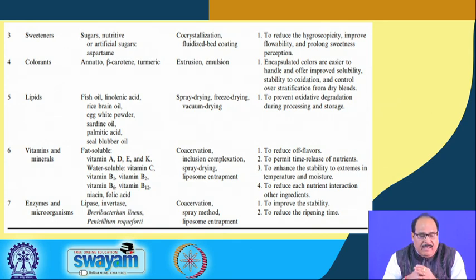Lipids like fish oil, linolenic acid, rice bran oil, egg white powders, etc. are spray dried or freeze dried or vacuum dried to encapsulate them, and these encapsulated forms are used to prevent oxidative degradation during processing and storage. Similarly, vitamins and minerals are encapsulated using coacervation process or inclusion complexation, spray drying, and such other methods.